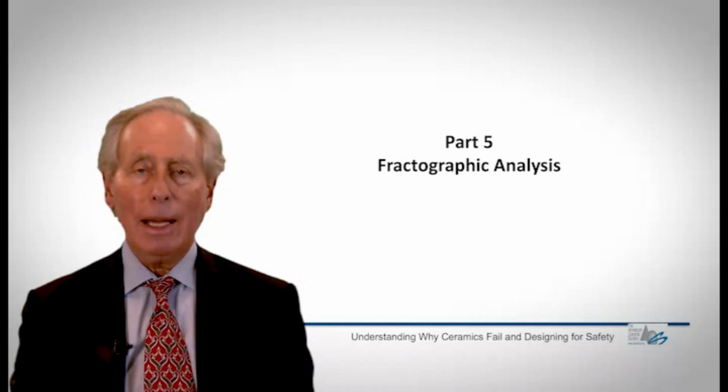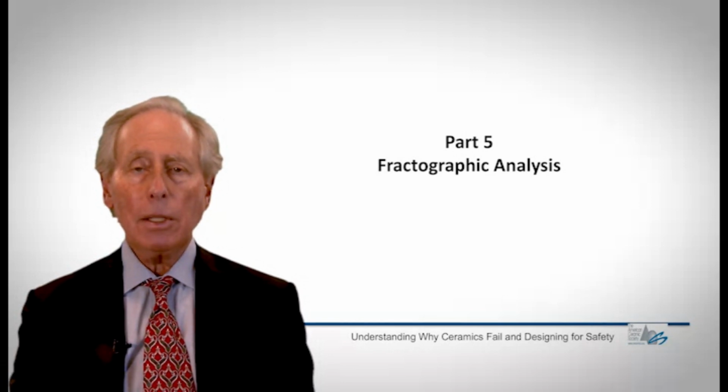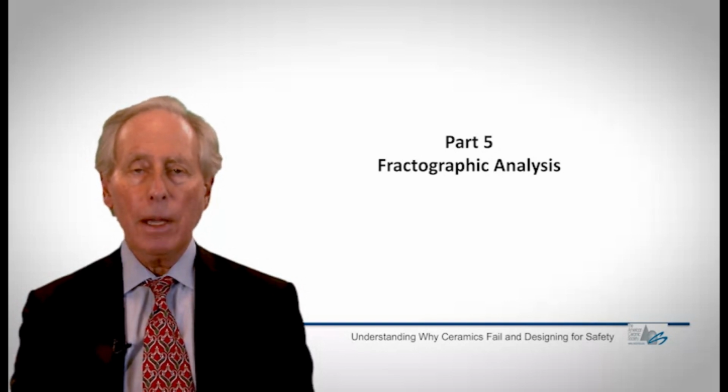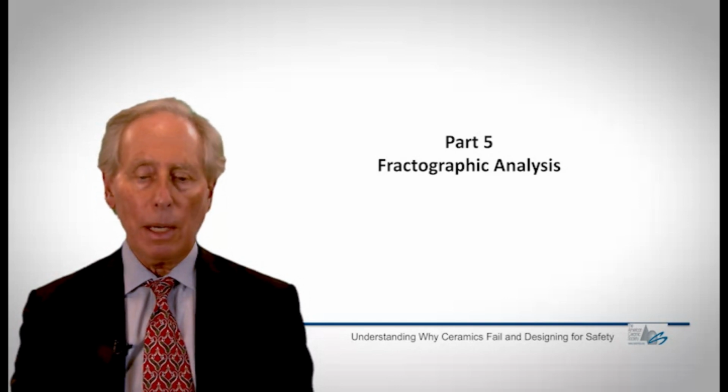In other words, what kind of defect was it, or what kind of scratch was it, how big was it, but it can also tell us a lot about the stress at fracture. There are quantitative aspects of features found on the fracture surface that are very important and are not always used to the greatest extent they could be in understanding what's going on in the fracture process.